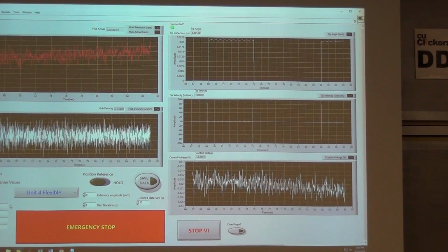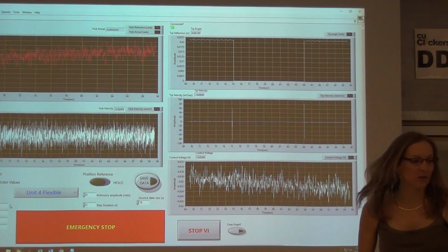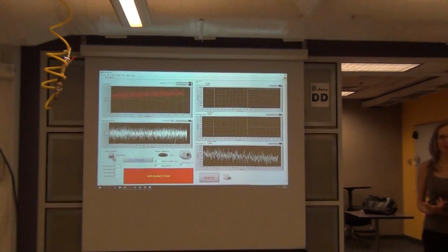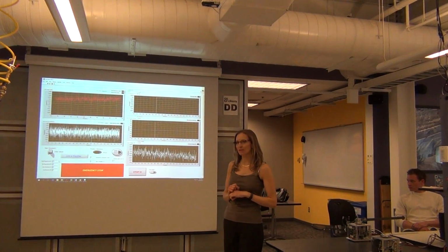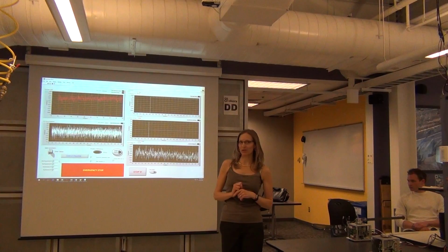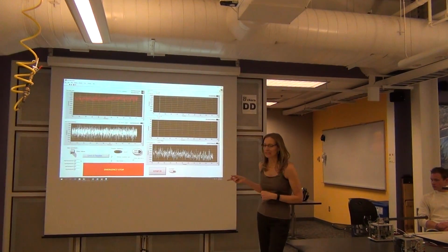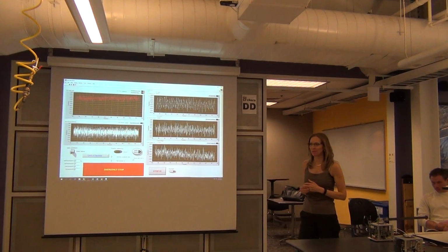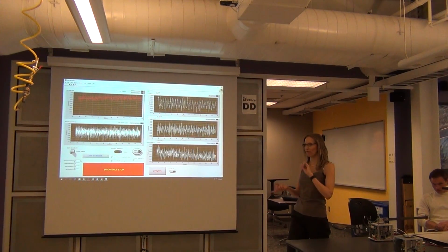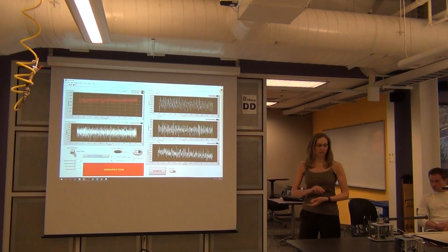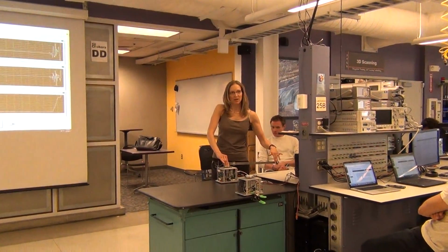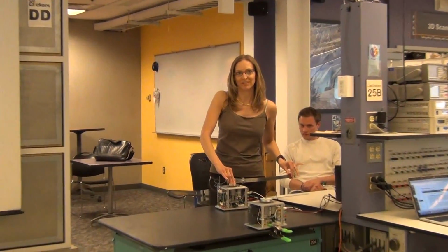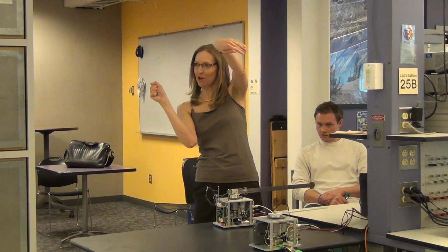Okay, all right. One thing I want to point out that kind of trips people up the first time is, remember before when I said negative gains were unstable? There's one exception to that, the K2 gain. K2 gain actually has to be negative in order to be stable. It's reversed of all the other gains. And the reason is, if you move the hub in one direction, the tip is going to go in the opposite direction. Just the way the dynamics work. If I move the root here, the tip's going to go this way.